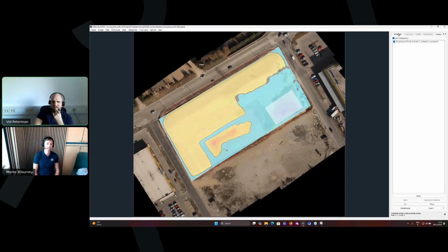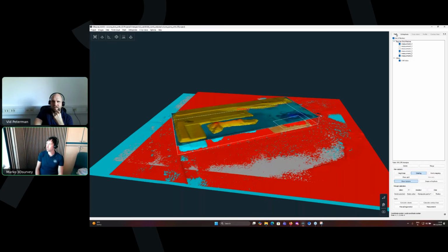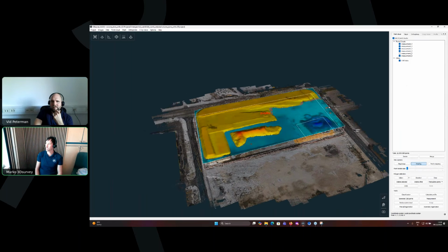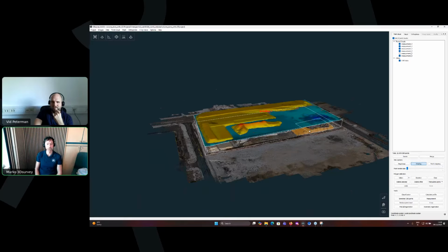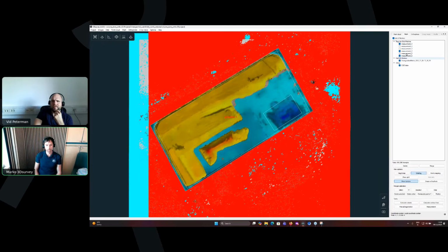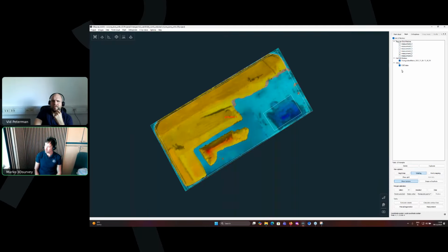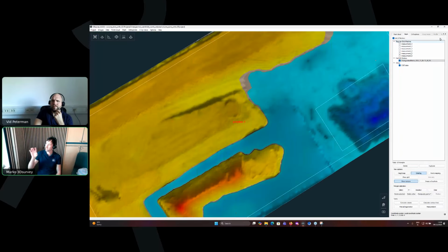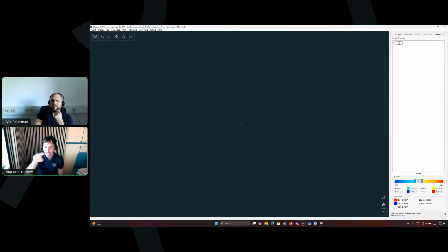I believe I understand this one. This is connected when you calculate a mesh from, let's say, a total station or GNSS. So the big triangle is the unit of triangulation, and it's hard to delete some triangles there. Okay. What I'm always telling customers: use the clip function. With the CAD, you can define your area of interest and clip this triangulated mesh from CAD data with the CAD boundary.